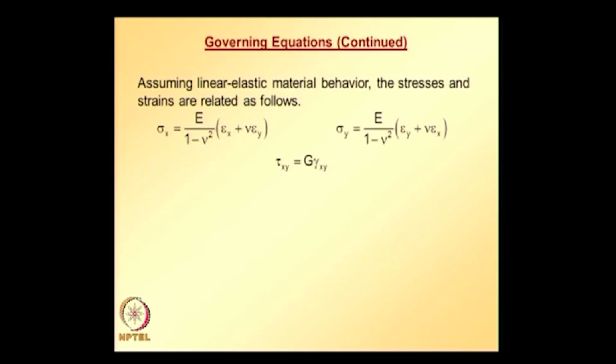And please note that we are looking at plane stress case. So, under plane stress conditions and under linear elastic material behavior, stresses are related to strains through these three equations. Three components of stresses are related to three components of strains through these relations, which we can write in a matrix form.